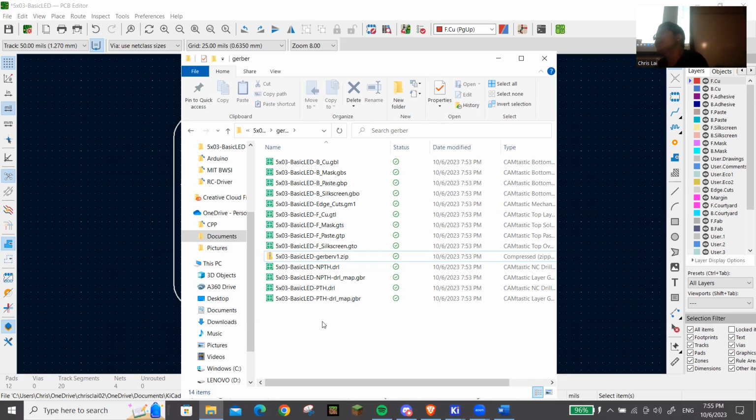Non-KiCAD. And generally, you don't want to auto route. Altium has a cheat code in which it does all this routing for you, but there is an art to routing, like a functional art. And Chase is going to say something about that, but there's a functional art to routing, and auto routers usually don't take that into account, right? They don't take into account maybe if you're designing something for RF and you need wireless communication, maybe they won't design the RF part exactly how you want it. And maybe they put some routes too close together, maybe too far apart.